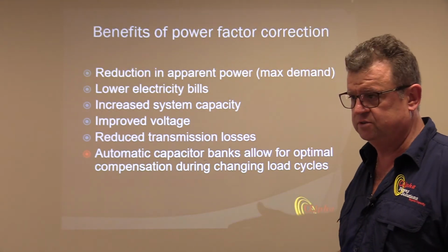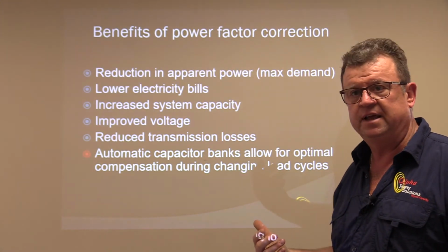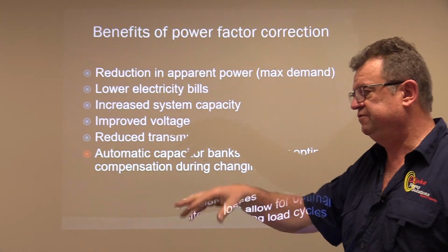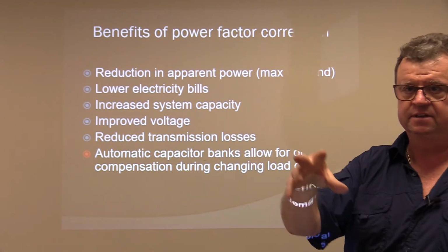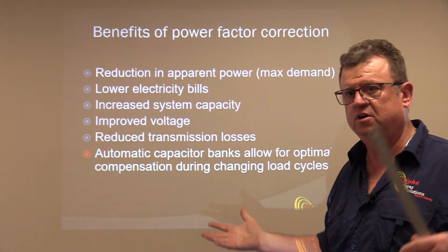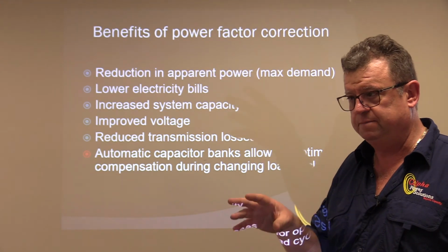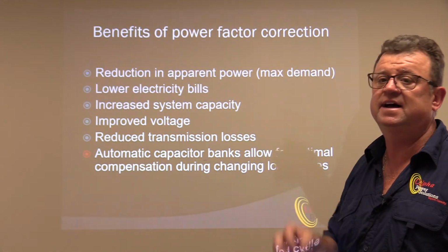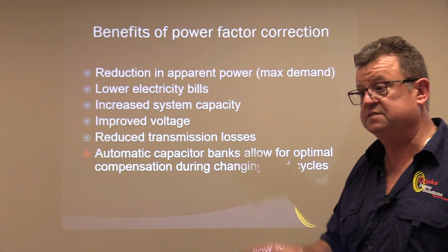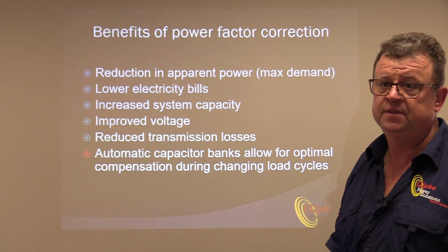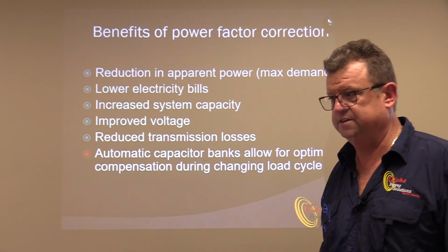We've done that with farmers or something like that, where the guy's got like a 100 kVA transformer supplying him, and he's got a massive borehole feeding a holding dam, and from the dam there's a pump feeding a center pivot. So there's only a few very large loads. In that particular instance, it's actually better to put capacitors, rightly sized capacitors, directly on the motor, so that the reactive power that the motor uses is manufactured at the motor. But in most instances, an automatic system is the cheapest way to go.